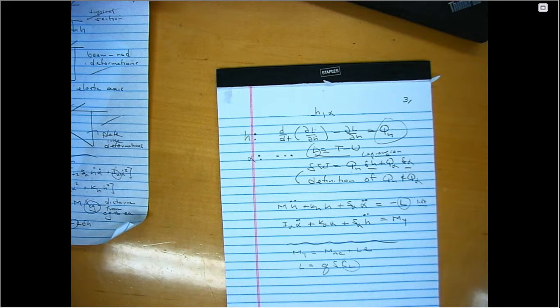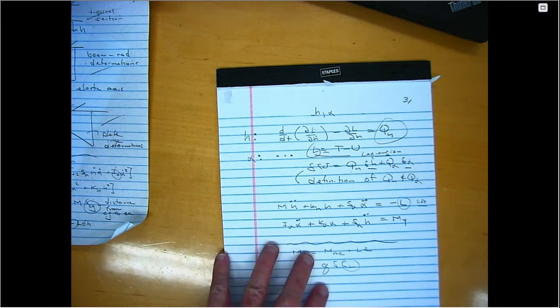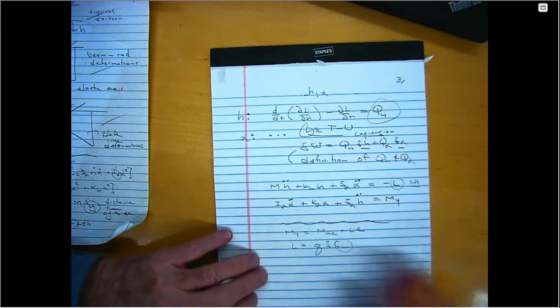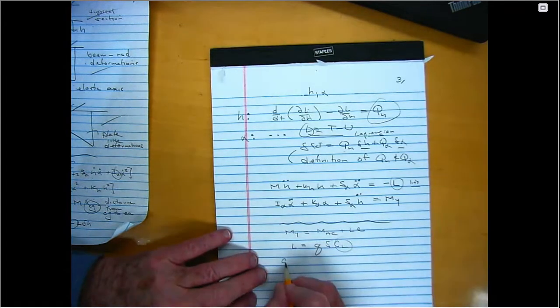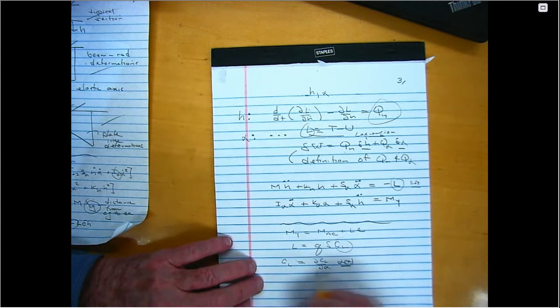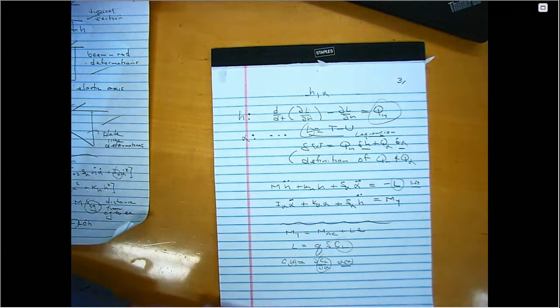Is that related to hysteresis? It's not really hysteresis, because this is a linear model, so there's no hysteresis per se. But it is a memory effect. In fact, let me write down a couple of relationships with C sub L. The simplest one is to say it's just dC_L d alpha times alpha, where this is the current time, right? And this is some constant. That's the simplest thing.